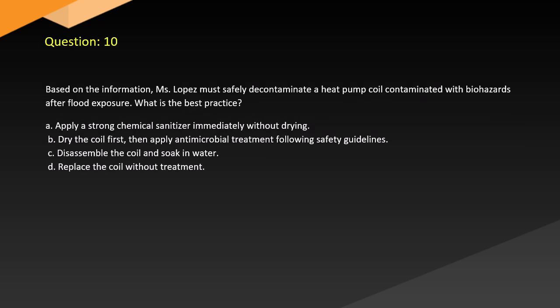Question 10. Based on the information, Ms. Lopez must safely decontaminate a heat pump coil contaminated with biohazards after flood exposure. What is the best practice? A. Apply a strong chemical sanitizer immediately without drying. B. Dry the coil first, then apply antimicrobial treatment following safety guidelines. C. Disassemble the coil and soak in water. D. Replace the coil without treatment.